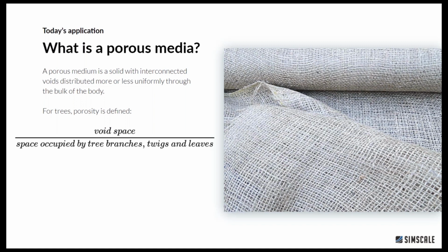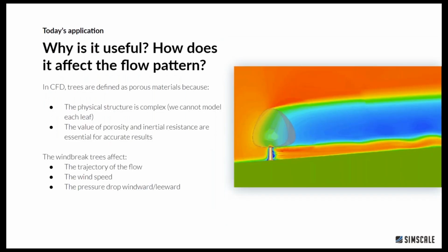In this specific type of analysis, that we call pedestrian wind comfort, we are talking about a specific type of flow that we call LBM, so Lattice Boltzmann method, and we're going to approach the porosity through this approach with different factors. So, for example, why is it useful, and why do we need to approach the porosity of trees with porous media? Why can't we just model it?